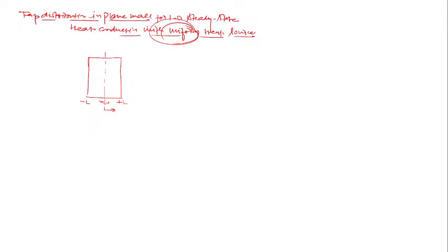And because there is uniform heat generation, obviously there is a Qg, then how should we write the differential equation? Now here area is constant, yes or no, and k is constant. They have not given any information about k, so it is constant. Then I can directly write the differential equation that we derived. For this case I can write d2T/dx2 plus qg dot upon k is equal to 1 by alpha into dT/dt, but it is 0 because of steady state. Now you can write.